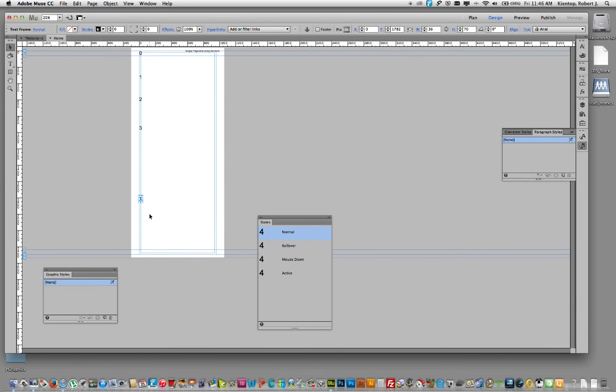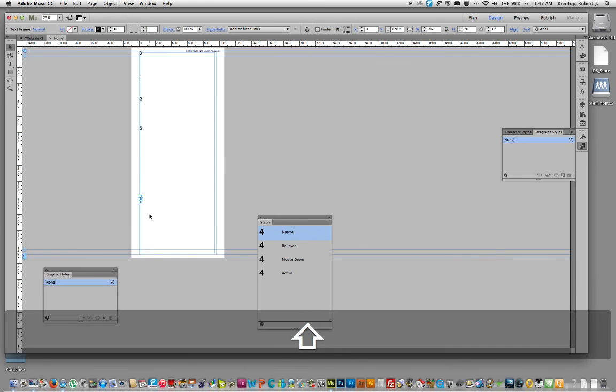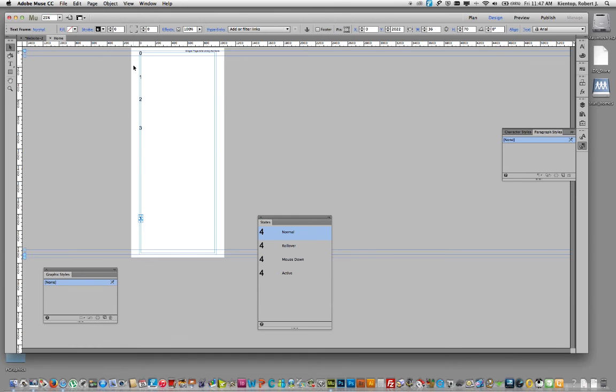I'm going to use the Shift down arrow to scrub that down to where I believe it should go, and just spread these out kind of uniquely. Highlight all of them, and then I'm going to visit the Align option. The Align option comes up over here. I'm just going to hit that and distribute these.